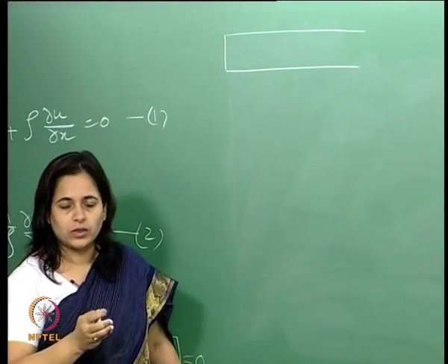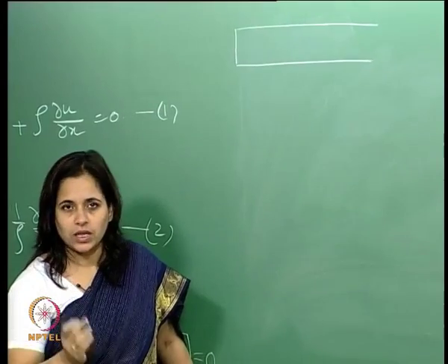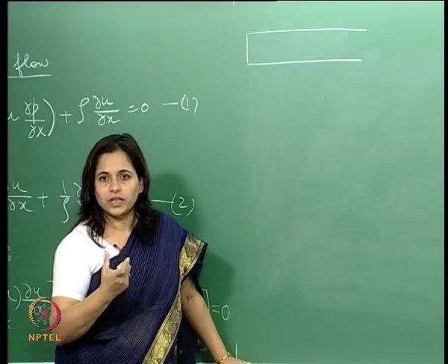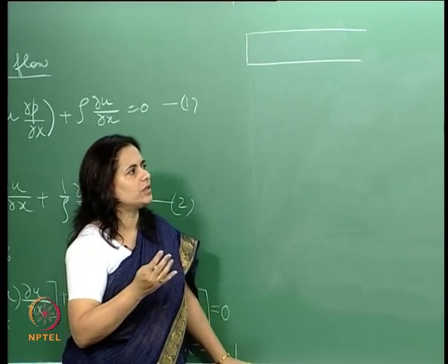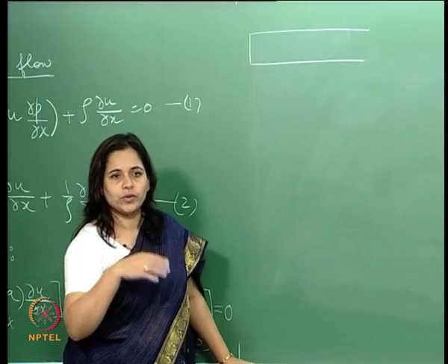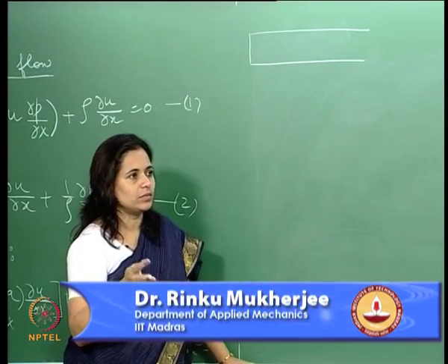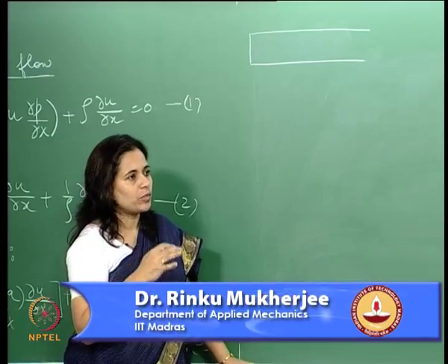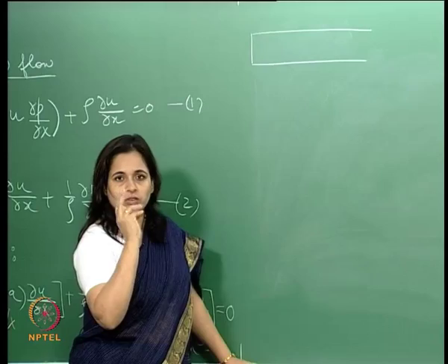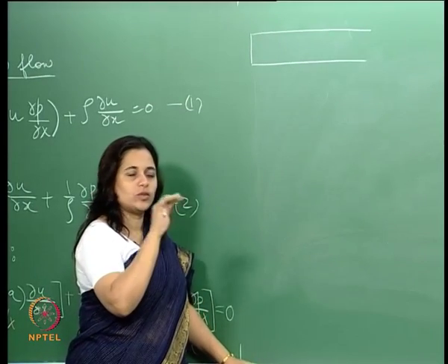So a shock tube is essentially two chambers in which you can have two different gases, or the same gas, under different conditions. They are separated by a diaphragm which we break by mechanical or electrical means at some point of time, and that sends a shock wave traveling to the right, moving into quiescent flow.